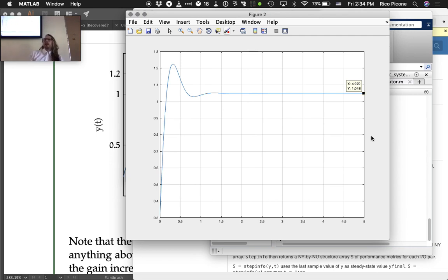But so we can't do anything about that now. But our overshoot here is certainly close to 20%, because we don't go down to 1. So the steady state is not a reflection of the complete percent overshoot. So this is probably about 20%, like we expected. And 19 is what the stepinfo function gave us. So this is pretty good.